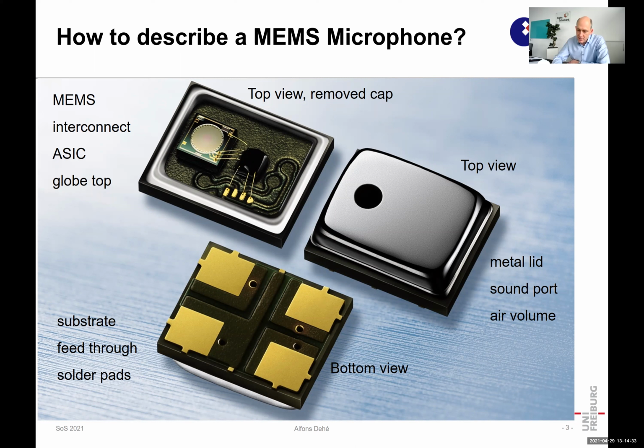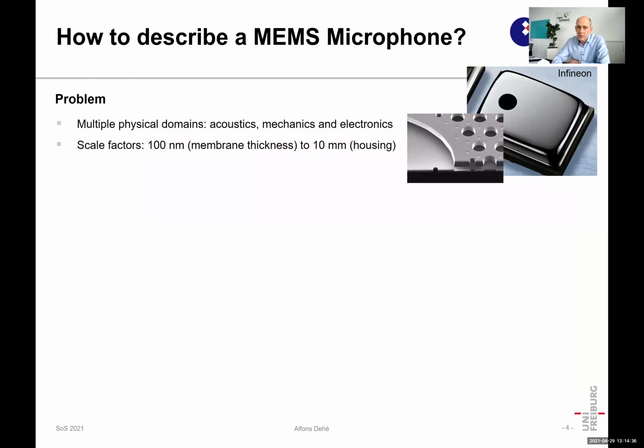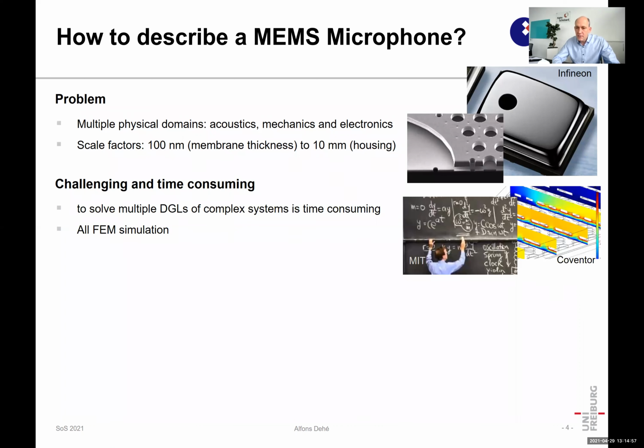And to simulate this is, of course, an issue if you look at the dimensions, so bridging hundreds of nanometers for tiny diaphragms up to housing, and the housing is also acoustically active. So this is not straightforward. You need to find the right way to do so. I know a lot of young students that are familiar with finite element analysis methods that go on such a system with just discretizing and doing FEM simulations. This is certainly something which is difficult due to the scales that we see.